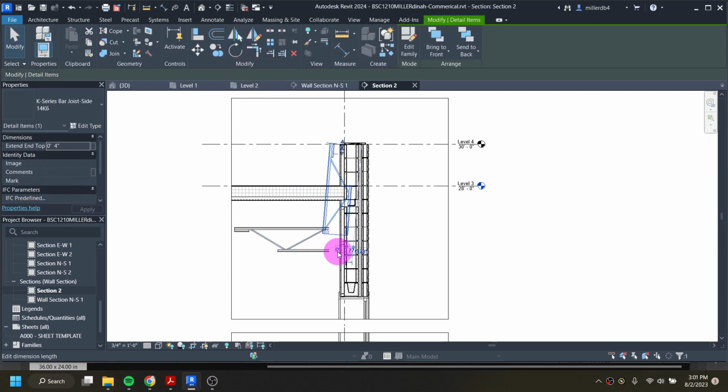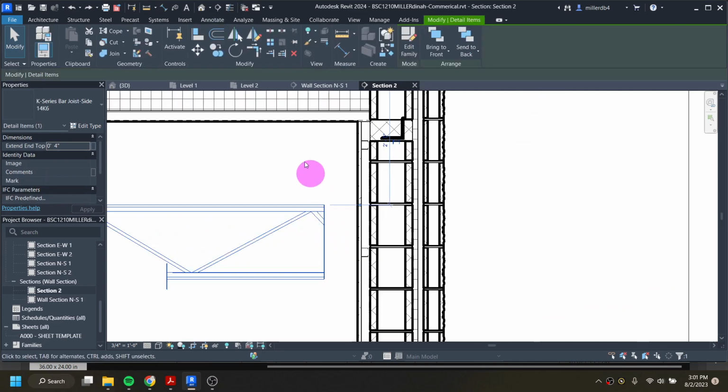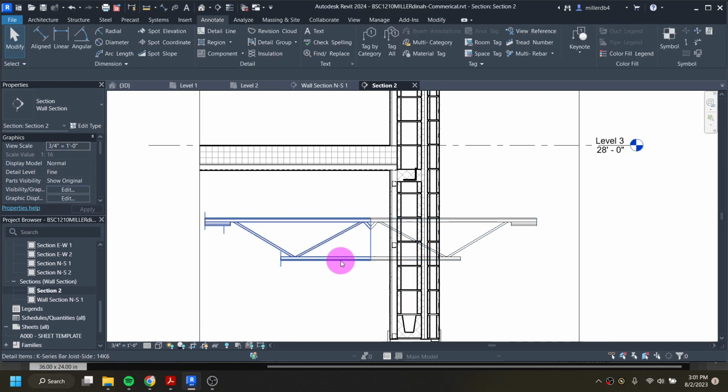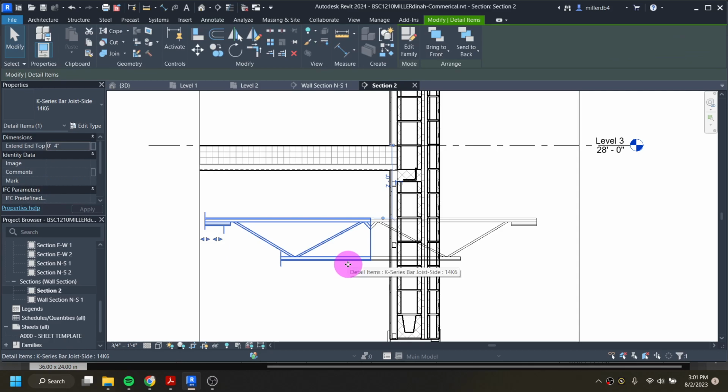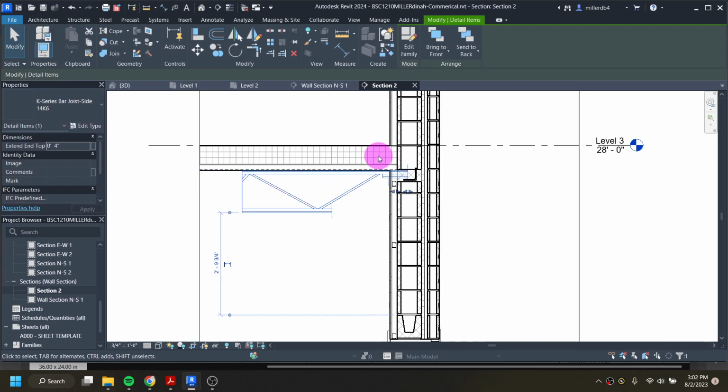And that will just be the axis I pick on, which I didn't click on the right thing. Pick axis, this line, and then I can hit escape, click on the original, delete it, click on this one, and kind of move it into place.